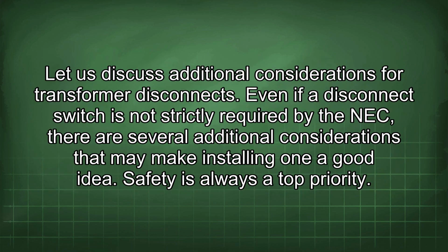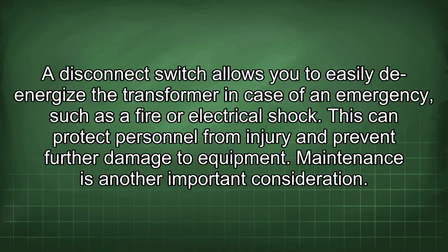Let us discuss additional considerations for transformer disconnects. Even if a disconnect switch is not strictly required by the NEC, there are several additional considerations that may make installing one a good idea. Safety is always a top priority. A disconnect switch allows you to easily de-energize the transformer in case of an emergency, such as a fire or electrical shock. This can protect personnel from injury and prevent further damage to equipment.